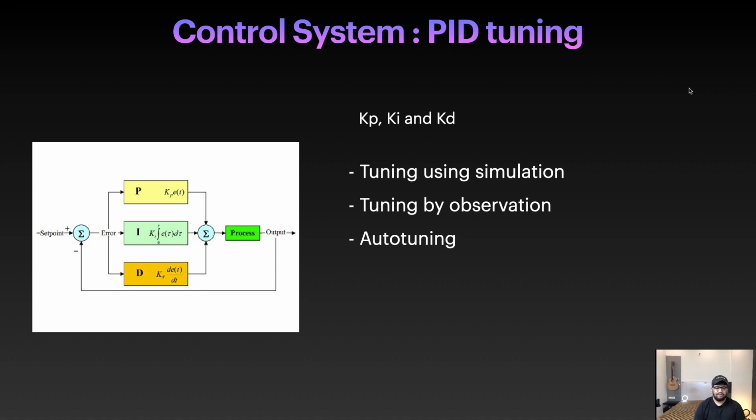and how your drone reacted. So based on that, you can bring that into the computer and you can see that, okay, I have given my drone a command and it takes 2 milliseconds to react. So it's a high delay, and you increase the Kp, things like that. And you also observe that, okay, now my drone is having vibration on this axis, so you can dial down. So this is another method which I used to do a few years back. But I would highly recommend you read more about it, especially tuning by observation and how to tune that. It's something which is very important, because the default values are not going to help for the longer run.